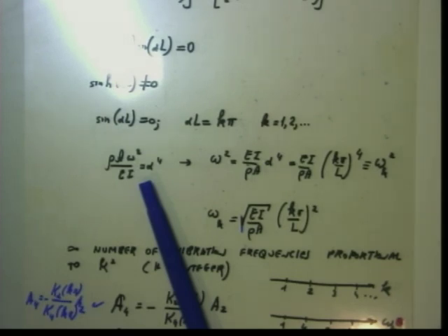Because this beam is a combination of an infinite amount of one degree of freedom systems, my answer is as follows. Calculate the response of each system and then sum them up. You will have an infinite summation, k from 1 to infinity. You may say that is a very tedious task. Yes, it is, but thanks God we have the computer, so we can program this summation and get the result.